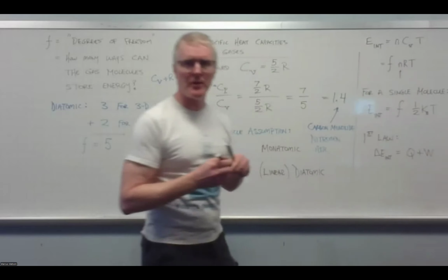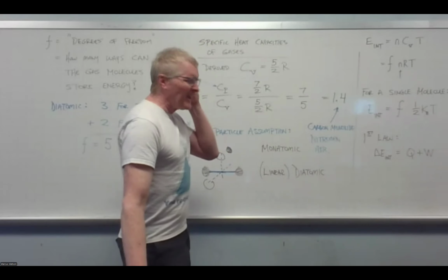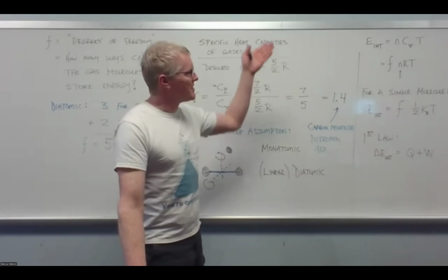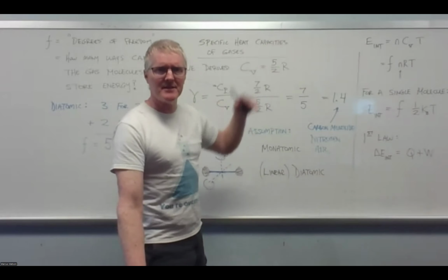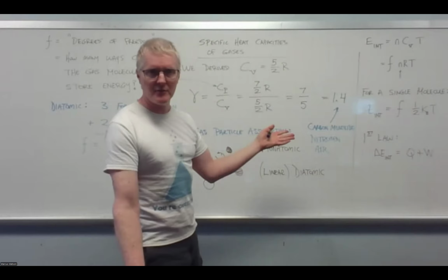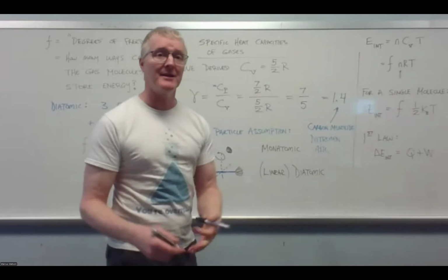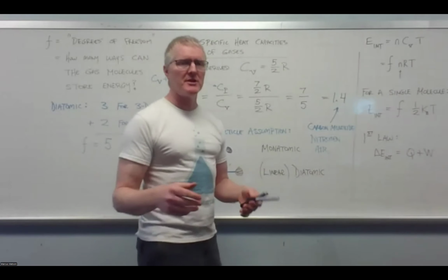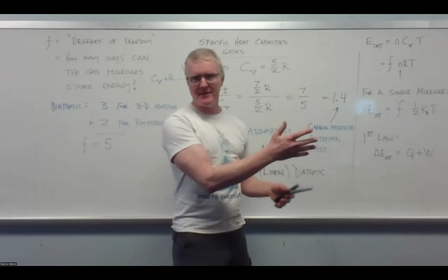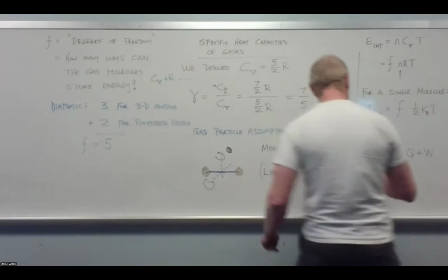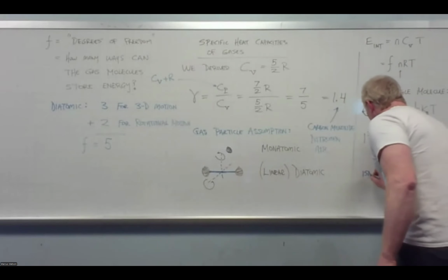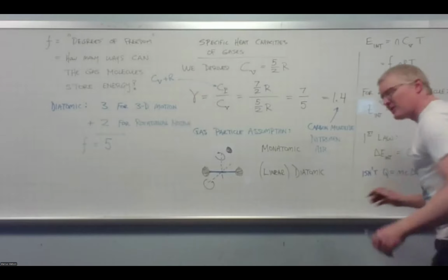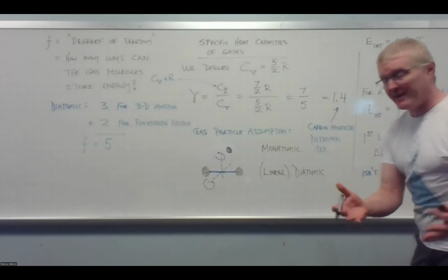okay, we have this going on. And you'd say, okay, well, if I calculate the internal energy change by using nCV delta T, how are we calculating the heat? Don't we calculate heat by using the molar version of mC delta T, the sensible heat equation, right? Isn't Q equal to mC delta T? And then we use the molar form of that, right?